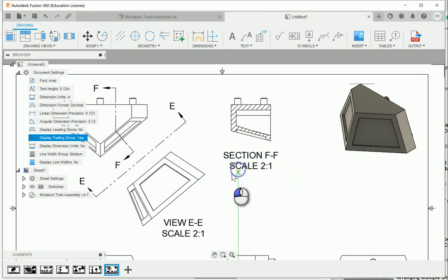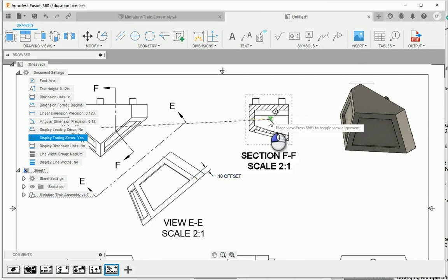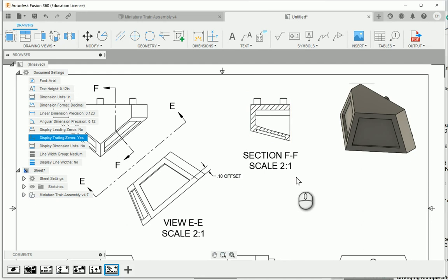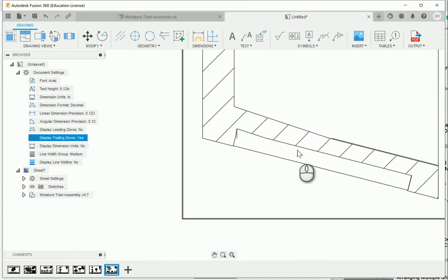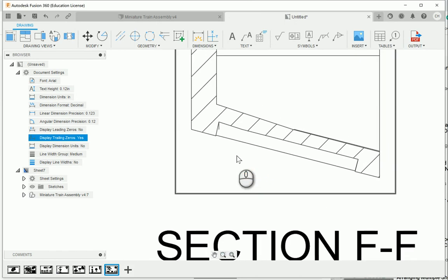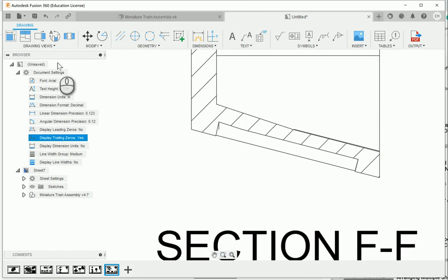Again, some of these dimensions may need to be moved around, or we may need to provide a little bit more room on our drawings. One of the dimensions that will be a little more difficult to pick up will be this 0.05 TYP, which is how far the front edge is cut in. So I'm going to use the dimension tool. The point you're looking for is, if you hover over this line, the end point of this line right here.